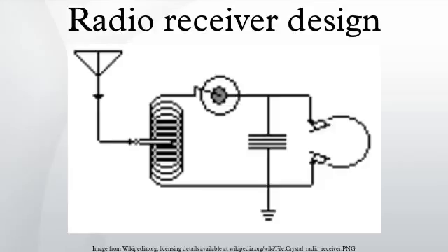Crystal radio. A crystal radio uses no active parts, it is powered only by the radio signal itself, whose detected power feeds headphones in order to be audible at all. In order to achieve even a minimal sensitivity, a crystal radio is limited to low frequencies using a large antenna. It relies on detection using some sort of semiconductor diode such as the original cat's whisker diode discovered long before the development of modern semiconductors. Advantages: simple, easy to make.